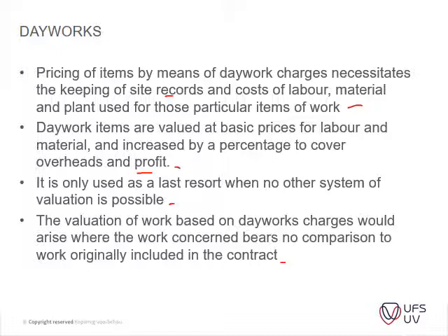If you have rates that you can use, it's easier and better to use bill rates for items completed. So it's best to have a completed item measured than reverting back to day works where you have to measure time and output and so on.